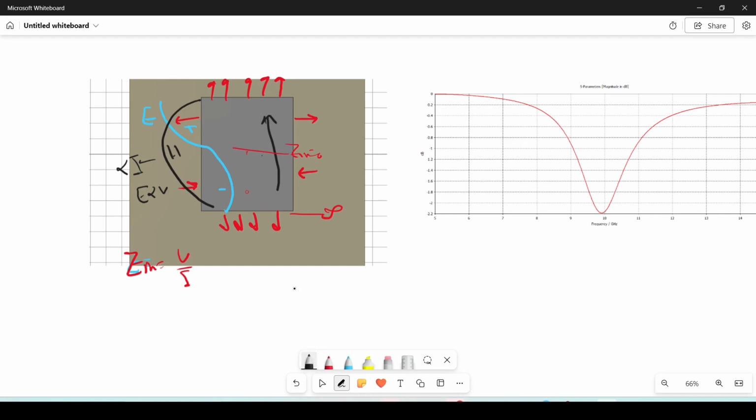And also you can look at it in a different way, honestly. If you have the ground here and here is the feeding, and you use the transmission line model, we have two impedances in parallel, like a short stub here and a long stub. So if we are feeding here in the middle, we have lambda over 4, and here is an open circuit, which is transformed like a short circuit. So we have Z input equals 0. And the same, if we are here, we can have directly infinity, right? So this is the point. We have to sweep generally between here and here.